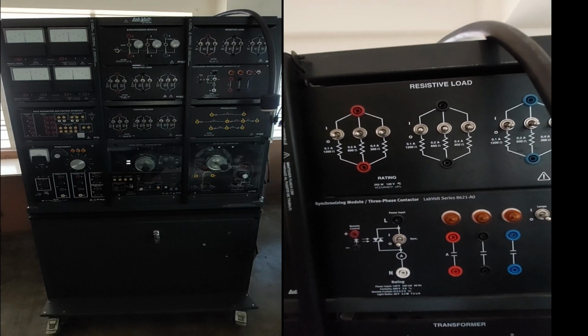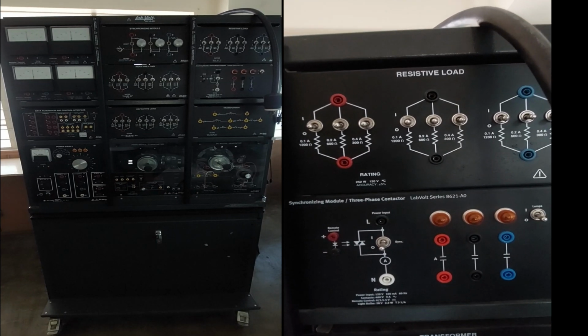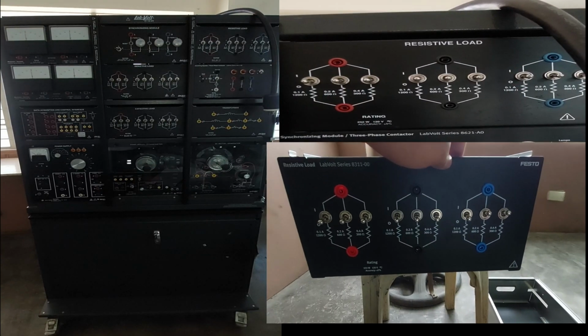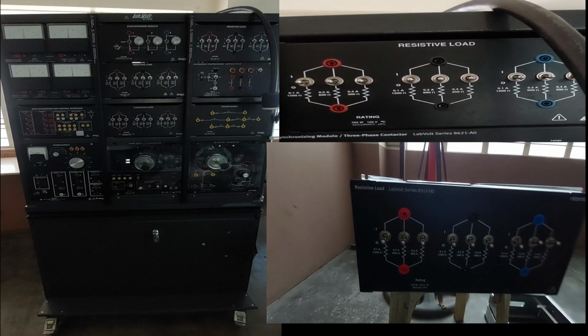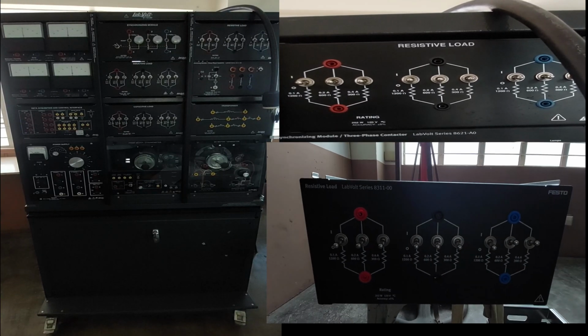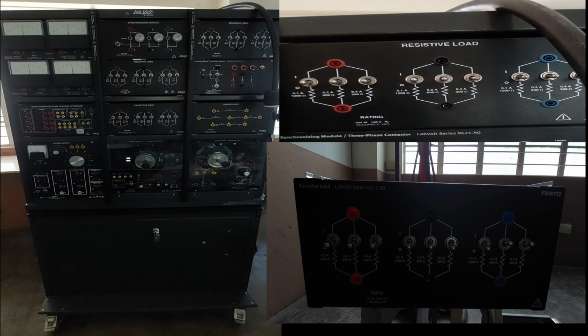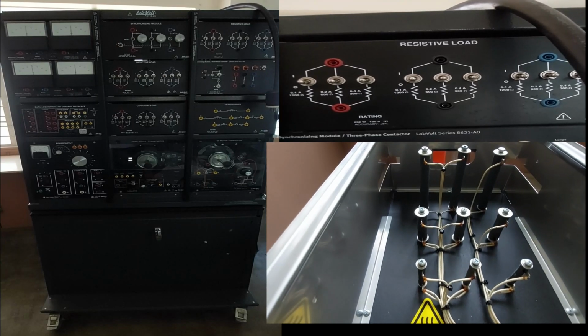The resistive load consists of a module housing 9 wire-wound power resistors arranged in 3 identical banks. Each bank consists of 3 resistors connected in parallel that can be switched on or off with toggle switches to obtain various resistance values. This allows the total equivalent resistance of each bank to be increased or decreased by steps.